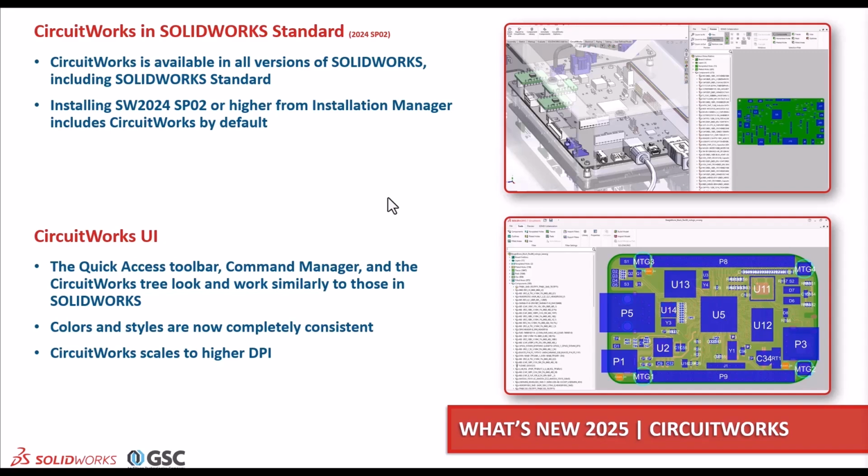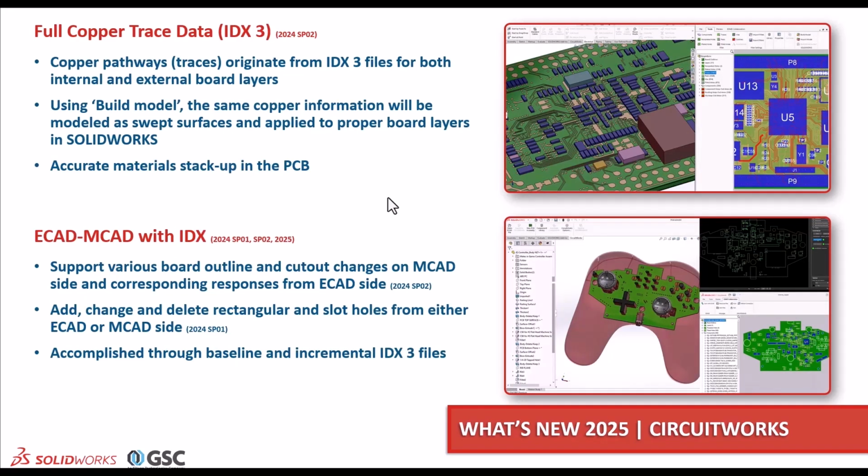If you're not familiar with CircuitWorks, this is an interface that lets you import PCB design data and visualize it in a SolidWorks mechanical assembly format. IDX3, I'll get into a little bit more details later, but this is a greatly improved file format over the old IDF, and that is part of the updated CircuitWorks as of 2024 SP2.